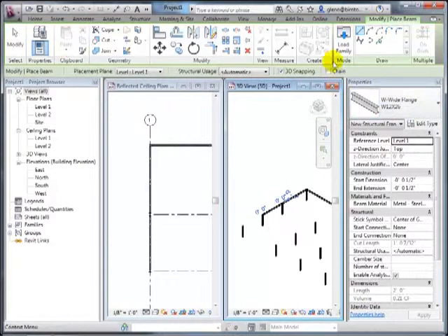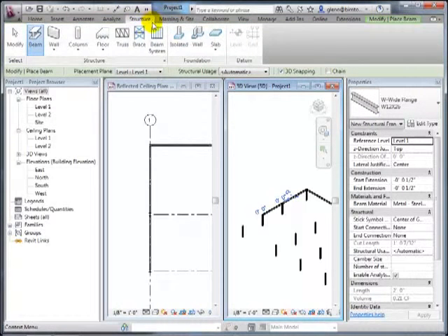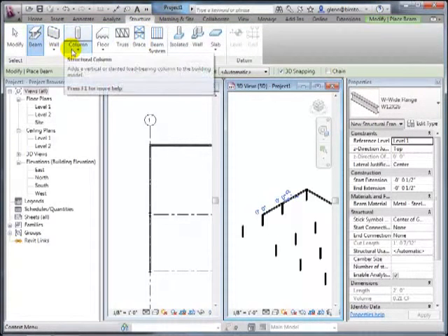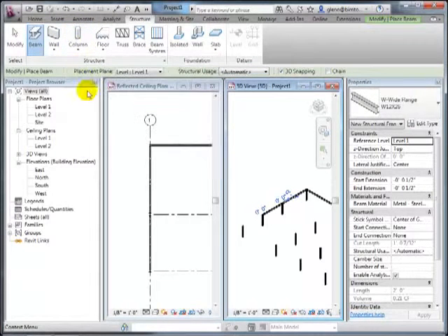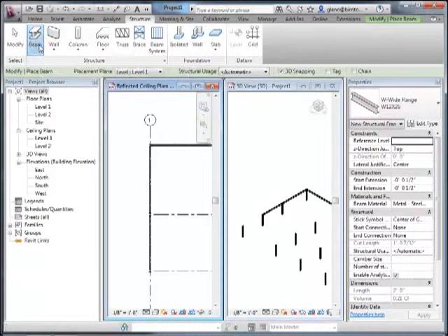Yes. So let's go there. And where you do that is you go to Structure. Kind of like the columns have shortcuts, beams tend to have shortcuts too. If you want to put a lot of beams all over your grid lines, you can do that. Let me come over here. I'll say beams. Beam basically has the choice.